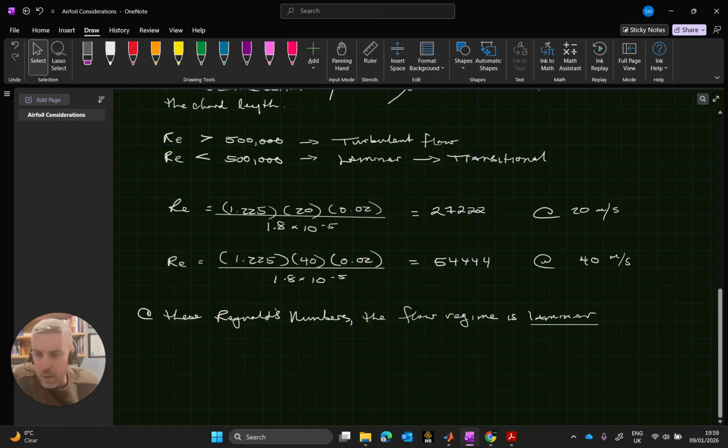I've had people say to me, oh, well, look, the Reynolds number is dimensionless. You can increase your velocity, or maybe increase your chord length to bring it up to 3 million. Right? You're at 54,000 on your higher one of 40 meters per second, to be safe, so we'll probably run with that. If you brought that up 20 times by 360 times, you could achieve what they have in the NACA. Yeah, maybe so, but that would be in no way as indicative of what would be happening on track. So what good would that be to me?